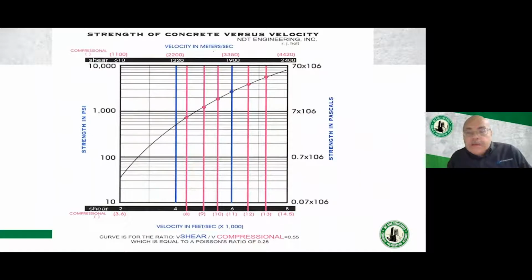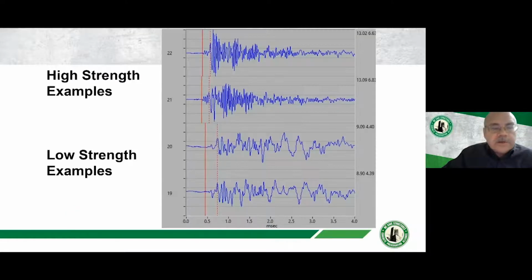And every time we pull the trigger, we move that 4-sensor array into another transect or another area. We're getting compressive strength over that sensor array area. It's correlated with cores very often. And we're within 500 PSI of a core that might be extracted in a preliminary phase of investigation, taken out of its element to a lab, broken under the ASTM compression standards, and we would compare very, very well to those results. So just 2 examples here.